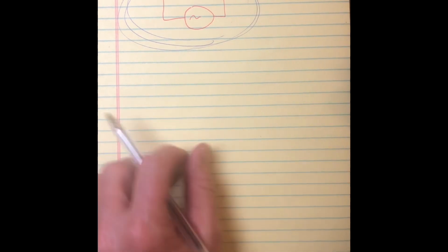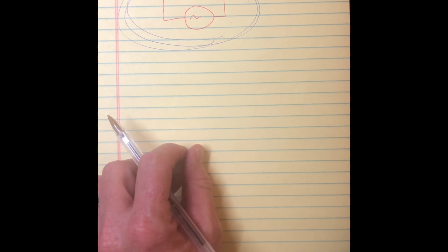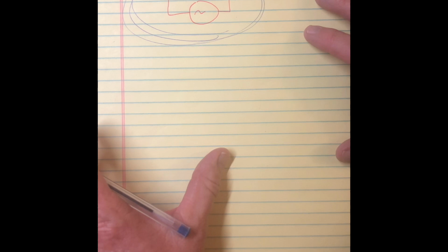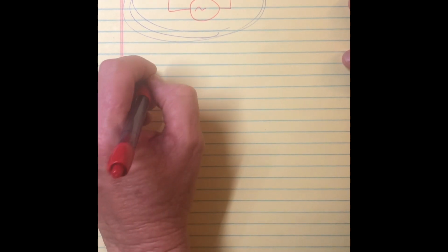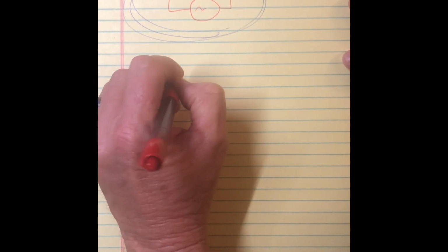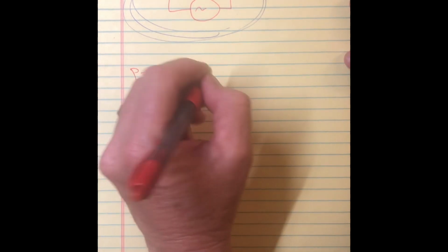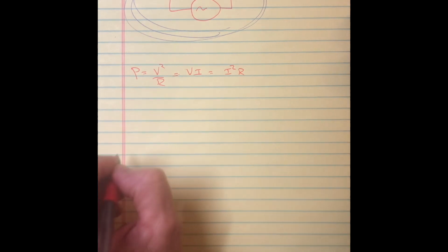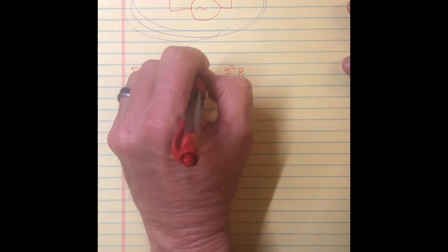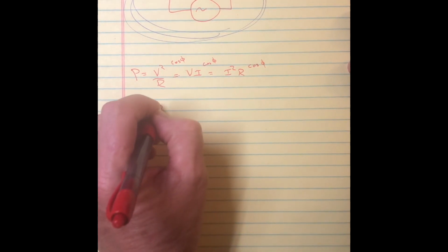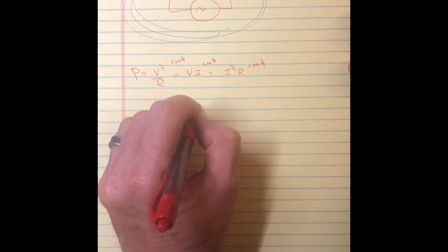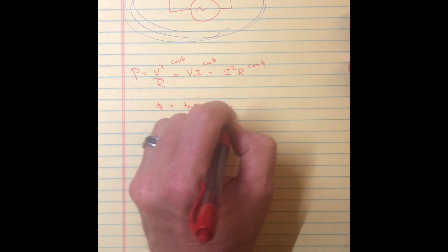So far, I haven't done too much about the AC circuits, other than I had to realize that they have to go one way and then the other, and how do I incorporate those diodes. But now I can get to the power in a circuit. The power is then V squared over R, or IV, or I squared R. I guess actually there's a cosine phi factor that we said showed up, where phi is that inverse tangent of XL minus XC over R.